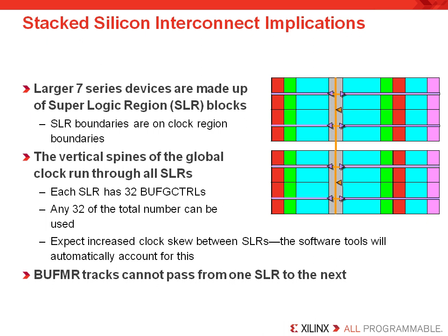So what we're trying to say is that, again, even the larger density FPGAs still only have 32 global clock routing resources. So although there are n by 32 BUFG controls in the complete device, because recall there are n devices to build up one large FPGA, each die can be thought of as being its own device. In this case, however, on a large device that has super logic regions, only 32 of the BUFG controls can be used. Because each SLR is a different die, its fabrication process can also vary from one die to another die. And this can mean there can be more skew than you might expect. Therefore, it is possible to see more skew on the global clock if it traverses multiple dies.